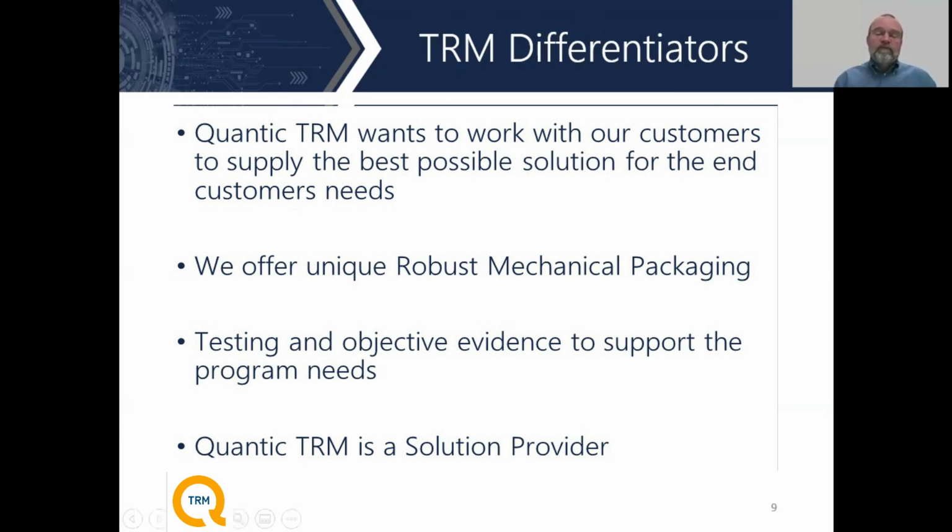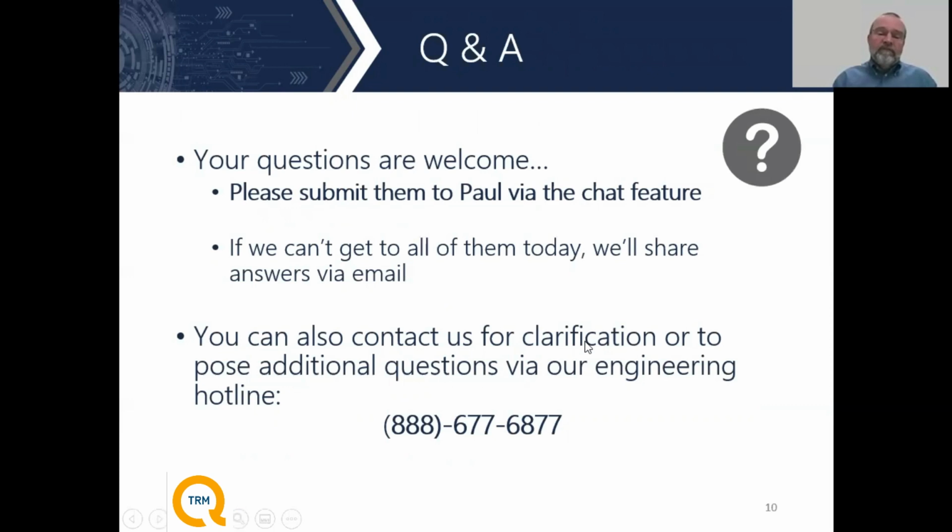Okay, and we do have a question. And it's something that I kind of wondered as I was listening today, because you talked a lot about thermal stability. So do other environments beyond temperature impact stability? Yeah, absolutely. And I think what jumps to mind here, Paul, is the air pressure, or altitude stability. One thing I think we kind of take for granted is that the environment is always going to have air around it. When you go up high in altitude, that is no longer the case. So stability for things like power handling varies widely when you change the air pressure.